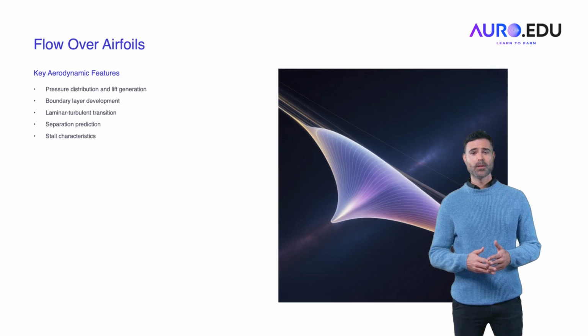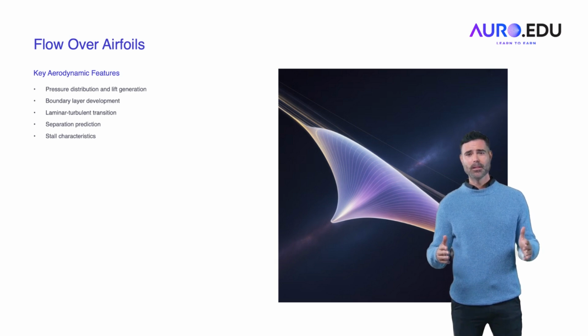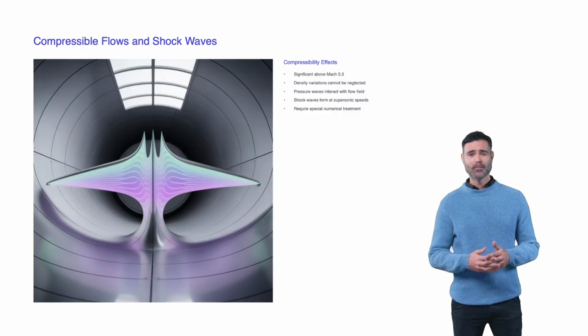Stall characteristics and critical angles of attack can be predicted by CFD, helping engineers design airfoils with better stall resistance and optimize performance. By simulating airflow, CFD allows engineers to visualize pressure distributions, separation points, and other critical flow features, which are difficult to measure in wind tunnels.